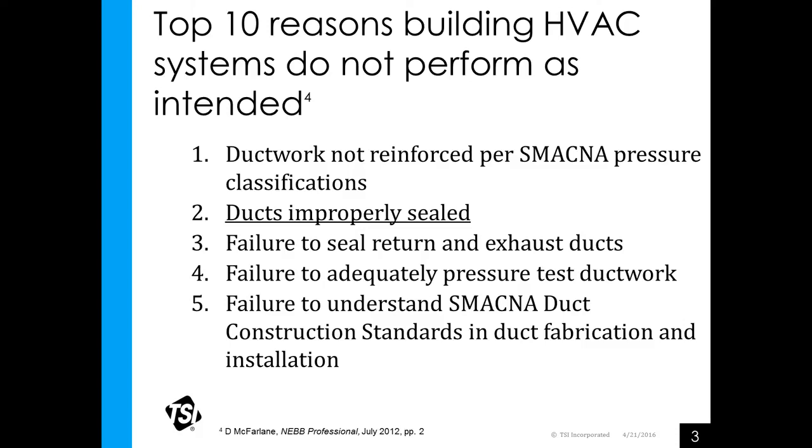Number one, ductwork. You can't have an HVAC system without some type of ductwork. And number one, ductwork we find normally is not reinforced to cover the SMACNA pressure classifications. Jobs are bid very, very tightly. Materials are constrained. They just don't do the job properly.